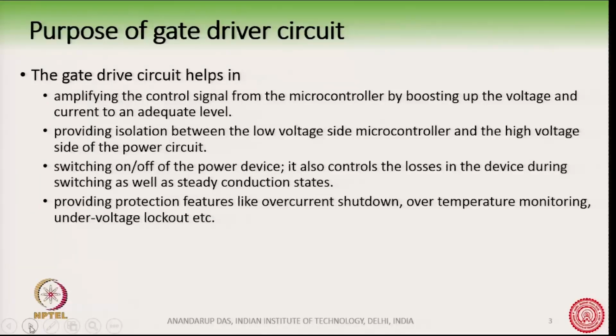Thirdly, the gate drivers can control the switching on and off of the power device. How fast the power device can turn on or turn off, the gate drivers have control over that, and that will again determine the switching loss in the device and hence the efficiency of the converter.